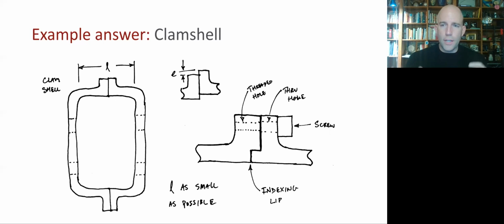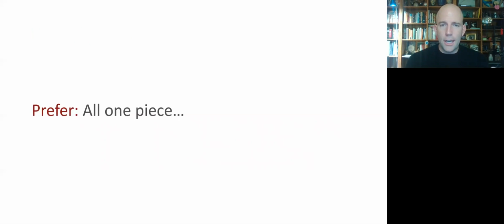Now, if you look at the free body diagrams for this, what you're going to see is both of these designs have the strength that those side plates have a good overall shape for, say, torque in that plane, or say 3-point bending or things like that, depending on how some other element was attaching them to torque those gears. So what we can see is as we start to break things apart, there are lots of new failure modes we have to consider, and especially thinking about force multipliers and error amplifiers will be important.